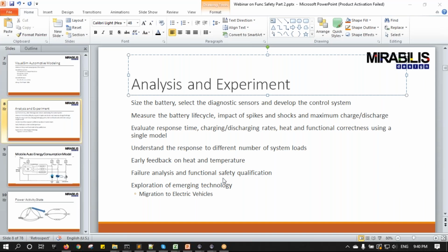Analyze which unit or sensor is responsible for power spikes and shocks. Analyze the response time for non-critical applications like ASIL-B applications and for critical applications like ASIL-D. And we have to check whether critical tasks were able to complete within a certain time, and whether the response times are deterministic. We can have an algorithm and we can analyze its performance with different use cases like increased load cases, etc.